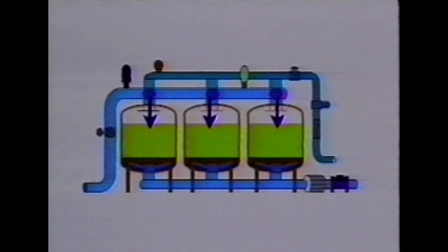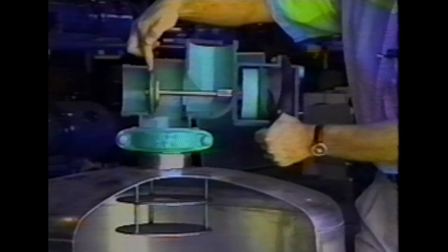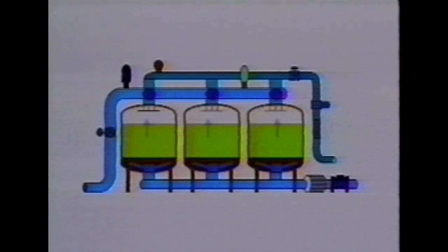During the filtration process, dirty water enters into the tank from the top. Remember that if there is a 3-tank system, 1/3 of the water flows through each tank. The water enters through a 3-way valve, which is then later repositioned during backflushing. After passing through the 3-way valve, water hits diffuser plates, which help distribute the water evenly over the top of the sand media.